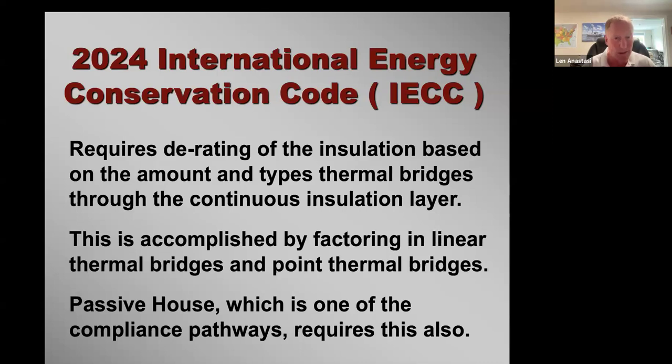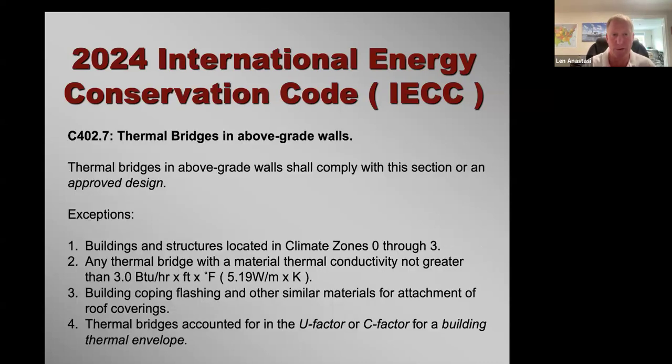This is accomplished by factoring linear thermal bridges and point thermal bridges. If anybody's worked on a passive house project, this is required under Passive House. They do this to get the true R value of your insulation in the wall. They factor in all these thermal bridges.